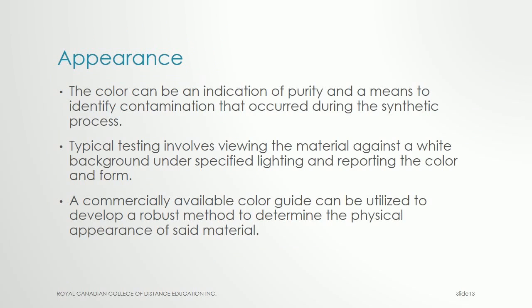Appearance. The color can be an indication of purity and a means to identify contamination that occurred during the synthetic process. Typical testing involves viewing the material against a white background under specified lighting and reporting the color and form. A commercially available color guide can be utilized to develop a robust method to determine the physical appearance of said material.